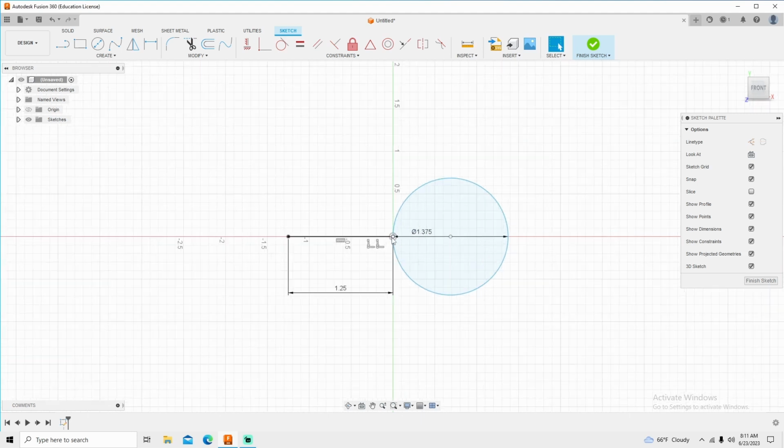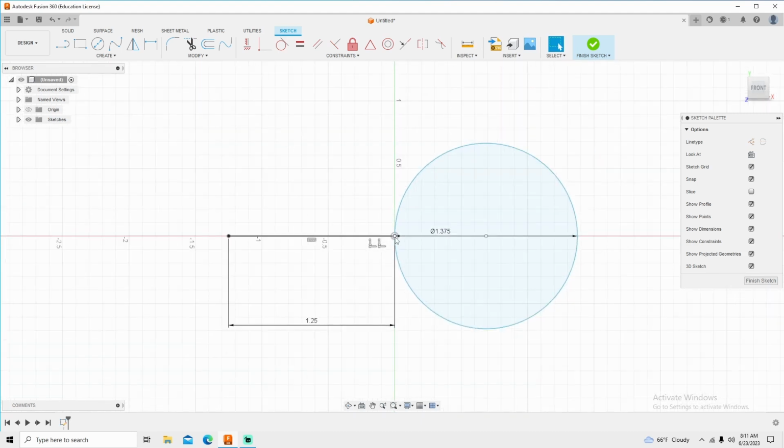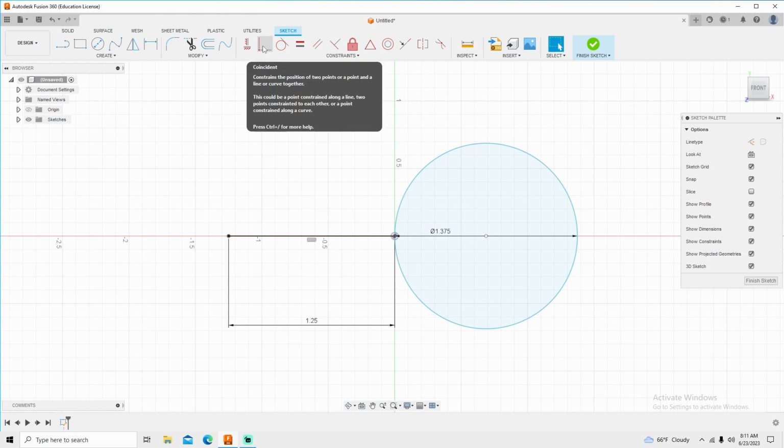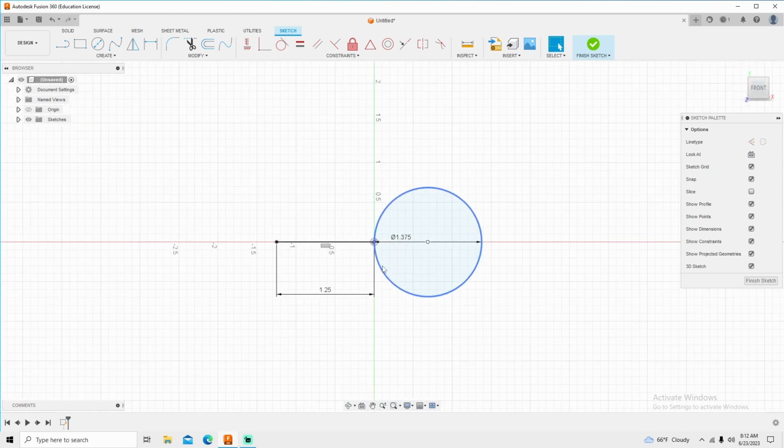And notice my constraint stays. Again, that's how we make sure things are staying put, is we use constraints. This constraint is called constant, which means you put it there, it now stays there. That's what that little icon right there that you're seeing just right there is. You can actually click on it, it'll tell you constant constraint. Now again, like I said, if you don't want to see the dimensions, but you want to keep them, turn your dimensions on and off.